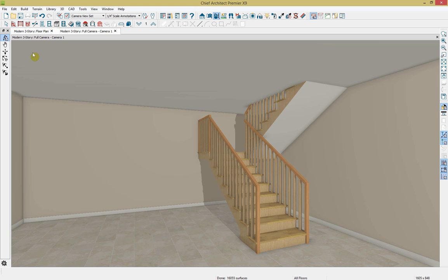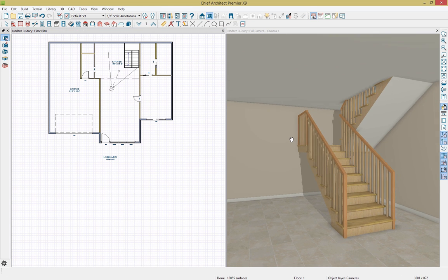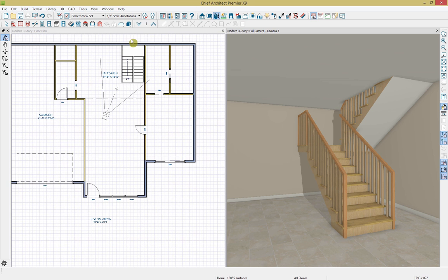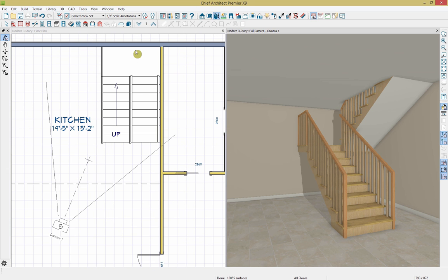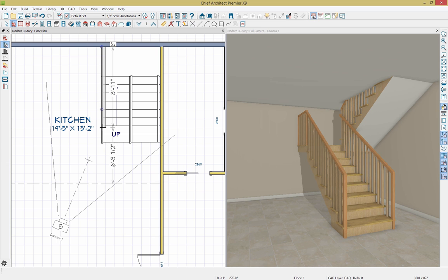And I'm going to tile vertically again, and we're going to drop in some walls underneath our stairs here. So I'll zoom in with the scroll wheel on my mouse, get into our straight wall and that interior wall, and then I can bring that right underneath our stair, and we'll just bring it maybe to that second tread there. And if you place that wall right underneath your stairs, it will automatically cut and go underneath there for you. So I'll do the same over on this side.